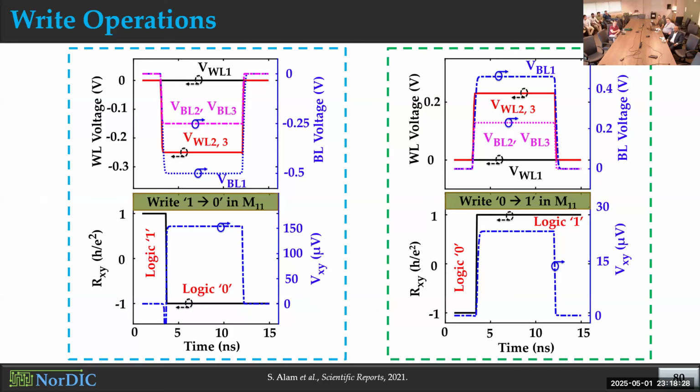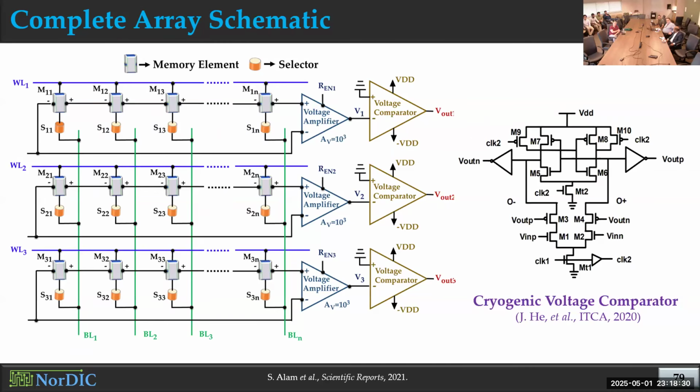I mean, isn't the voltage amplifier followed by the comparator basically those two blocks cascaded? Isn't that basically a sense amp? Yes, a voltage sense amplifier, but here we need large amplification, at least 1,000 times amplification. That's why we use the dedicated amplifier here, just to show that. And you're right, if you combine these two, I smell a sense amp. Yes.